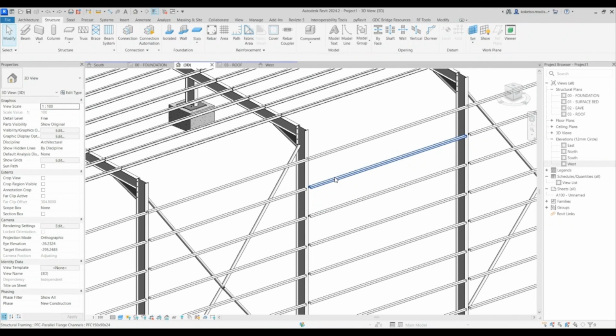So as you can see, it finished placing those connections. Now the last thing to connect is our bracings. So for our bracings, we are going to leave this part. We are not going to connect this part. We are just going to connect our bracings towards our columns. So I'm going to say connections, and I'm going to scroll down. And as you can see, we have different options. So I'm going to go with single tube brace angle and kidney hole. And press enter, and then it's gonna place this one, and I'm gonna select it, right click, and propagate connection, and obviously those connections are gonna be copied towards the other bracings.